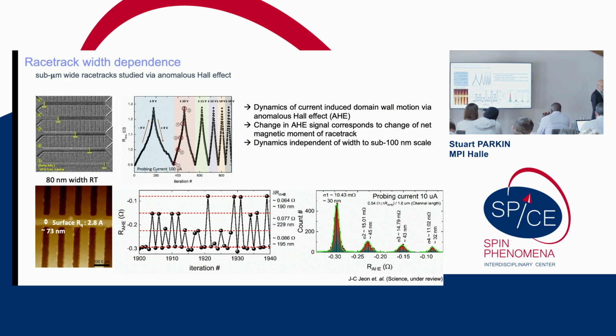And this is also very nice, and so in this way we can position individual domain walls with an accuracy of a few tens of nanometers, separated from each other by about 100 nanometers. These are exactly the technologically relevant length scales. If we can do this, and if we can, as I said, have a low enough critical current density, we could use Racetrack in a horizontal form to replace today's NAND. So this would be a major achievement.